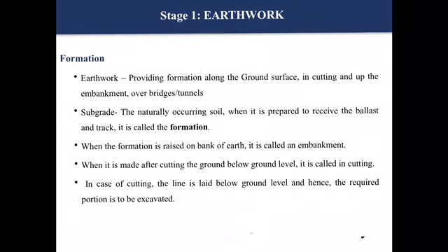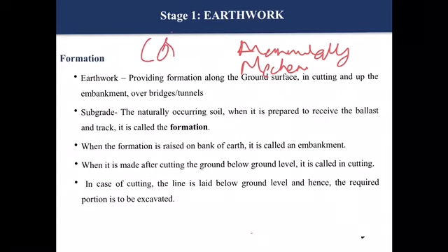In light earthwork, the excavations or the earthwork will be carried out manually, whereas if heavy earthwork is involved, we will go for the use of machineries to do your earthwork. And now, what is the cost of earthwork? That depends upon three main parameters. The first one is the type of soil. The second one is the hauling distance, and the third parameter is lift.